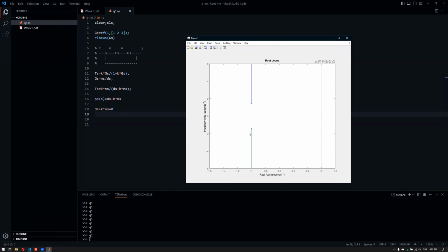So it gives us a visualization of the link between the controller gain K of a P-type controller in a unit feedback setup and the poles of that closed loop transfer function. So this is quite important. When you have Root-locus, you're basically at the first step of designing a controller, the easiest controller, the P-type controller. So that's already called control system design, and this is why we start with the Root-locus plot here.